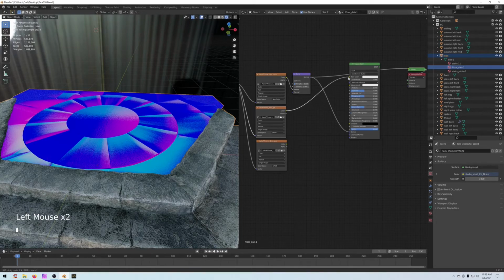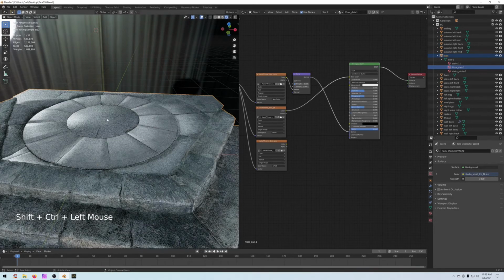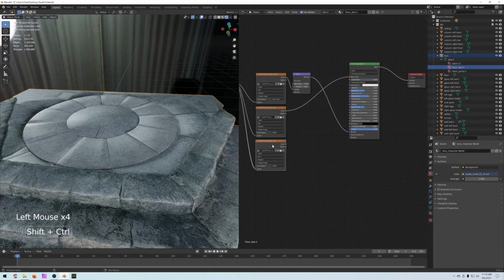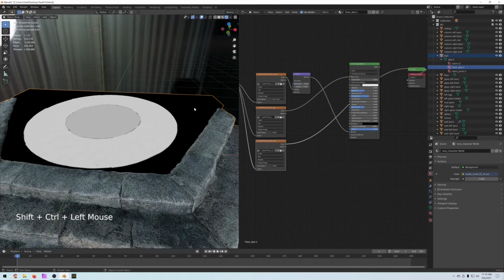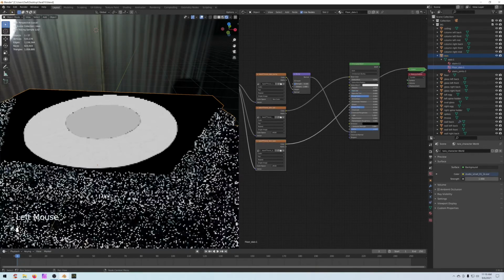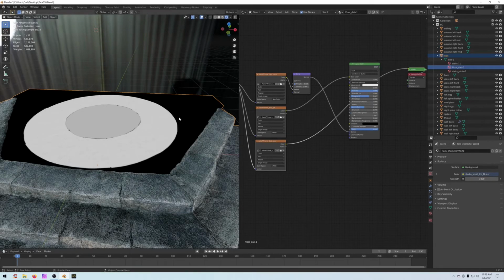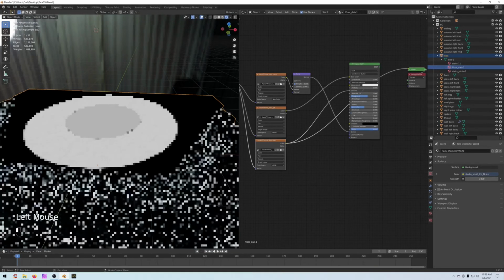And then the base color, very shiny, which should not be. Oh, we have a specularity map, so we'll isolate that and see what we have. So for the specularity map, black is 0 and 1 is white. So when we hook this up to specularity, we should have basically 0 glossiness on this black area and very bright glossy on this area, which I don't know if that's what we're looking for, but since it was included, we'll see how it looks.